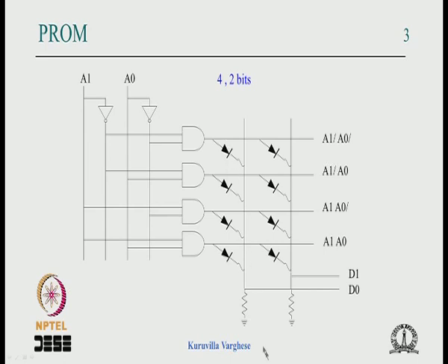Earlier the potential difference was somewhere around 5 volt, a little less than 5 volt. Now it will be around 9 volt, because it is double with some drops removed, or near to 10 volt. So the current flowing through the fuse is double that of the normal current and it will blow the fuse, and just for a short duration a negative pulse is applied.